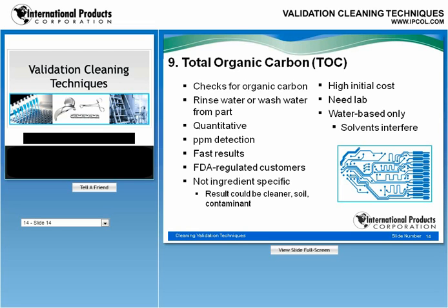These instruments are higher cost than everything we've talked about thus far. Ideally, they're suited for laboratory work, and these only work on water-based cleaners. Oftentimes, solvents are used as a final rinse solution. If this is the case, then total organic carbon is not an appropriate cleaning validation technique.